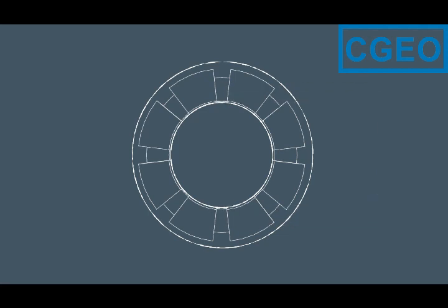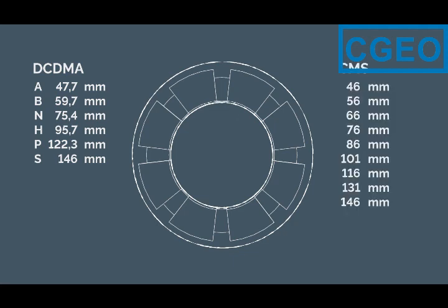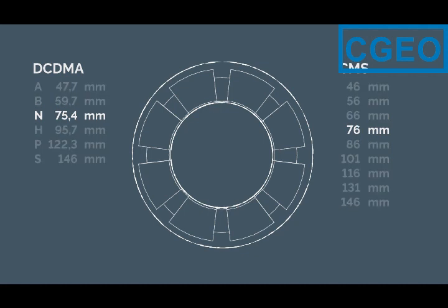The DCDMA system has a total of 6 different main sizes, each with their own letter. The Craelius metric standard has a number of standard sizes, some of which correspond to the DCDMA system. The abbreviations in the DCDMA system include, first, a letter for the size, N in this case, a letter for the company, and some more letters for the design. Here, EX stands for X-Core.